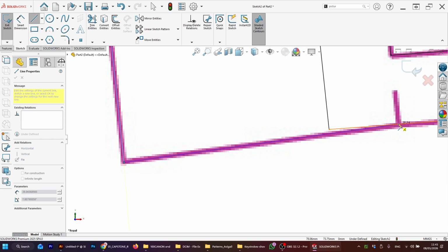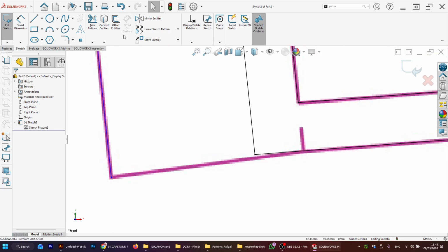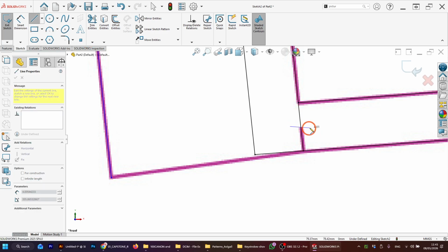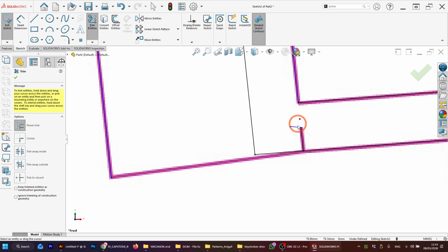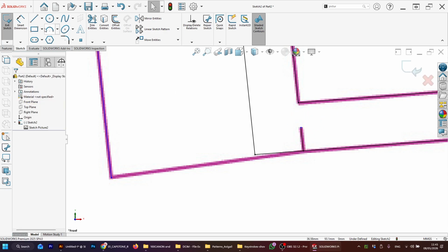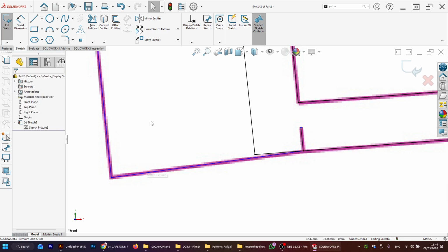And I go back here. Here I should do the same. So I can always do escape, go back to extend. This way I have the pick mark perfectly placed and spaced. Trim entities, cut all what I don't need, and now I get the perfect point. I can click that point, connect it to the end. Yes, it's a little slower, but it's perfect.